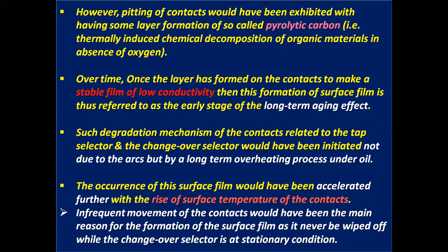Such degradation mechanism of the contacts related to the tap selectors and changeover selector would have been initiated not due to the arcs but by a long-term overheating process under oil.